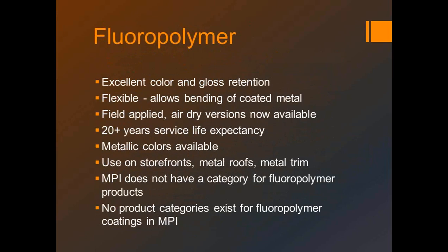You raise a good point there, Lewis, because what we're going on top of and what kind of surface prep you want to do will determine what kind of paint system we might recommend. You could go back to fluoropolymers, but in that kind of situation, I think your surface preparation is going to get out of hand in terms of cost to move up to a fluoropolymer. So if you have an acrylic system on there to begin with, you may just want to go back with an acrylic system another time around. That's one of the things we have to look at, especially on storefronts.